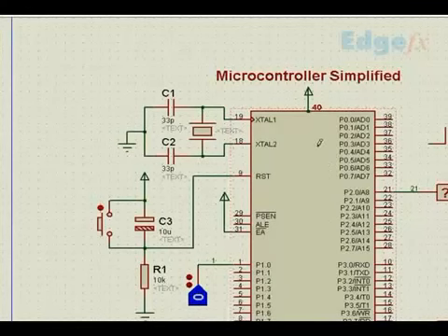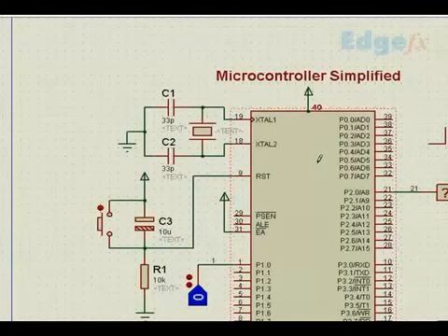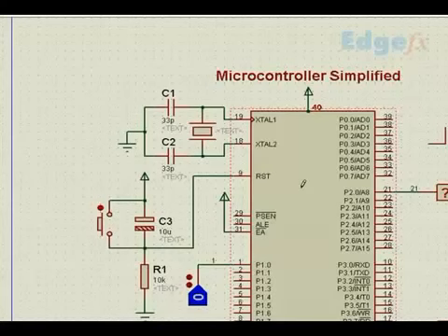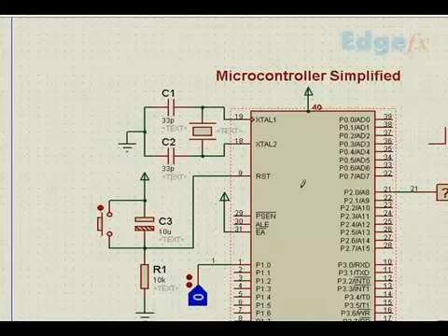We have taken a typical microcontroller here. It's being manufactured by many companies, but we have taken a microcontroller from the Atmel series. Atmel is a company, and this is called the family of microcontroller. 8051 is the most popular, and almost 70 to 80% of the microcontrollers used are Atmel 8051 series. It's the generic name, but the actual numbers will vary depending on the features inside. It is sometimes called 89C51, 89C52, 89S51, 89S52, and so on.